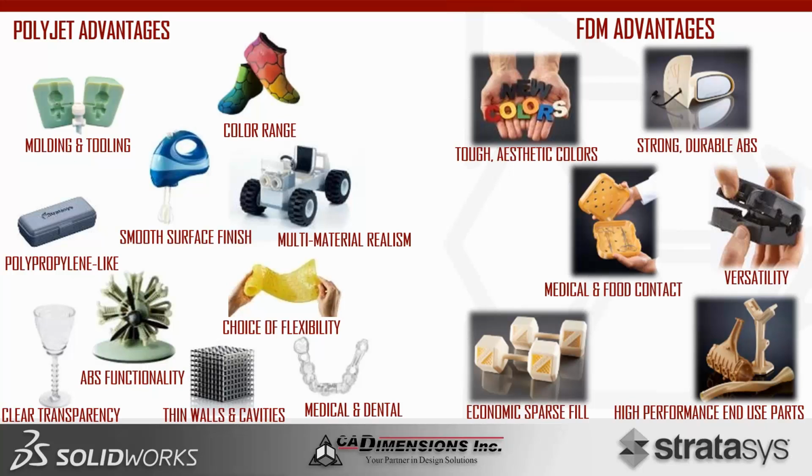That isn't to say that PolyJet can't be used for strong and durable parts. Digital ABS, as we just saw in the Berker video, is kind of a testament to that. But typically speaking, PolyJet is considered to be more so used for shiny, tiny, and pretty applications. So complex geometries and prototypes and models that require a high resolution, because there is a higher resolution with PolyJet due to the technology. Although it is important to note that the accuracies of the technologies are fairly similar.